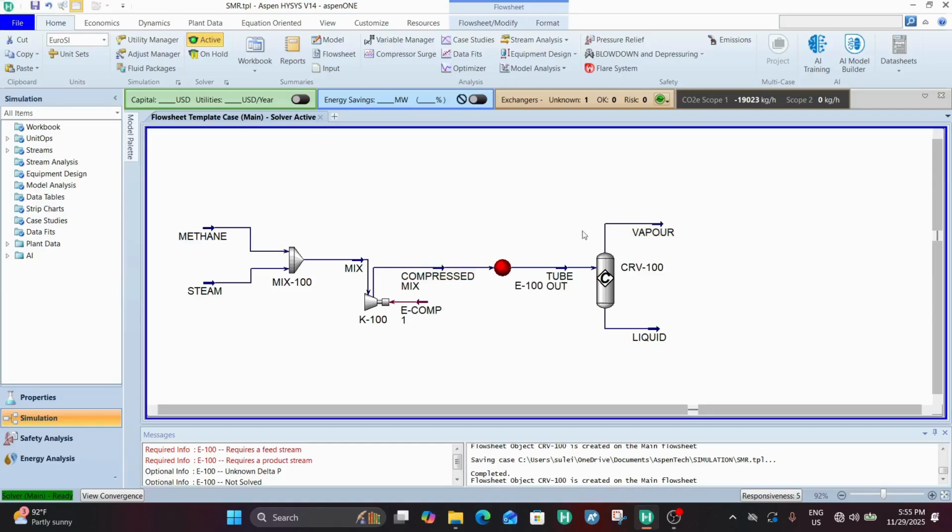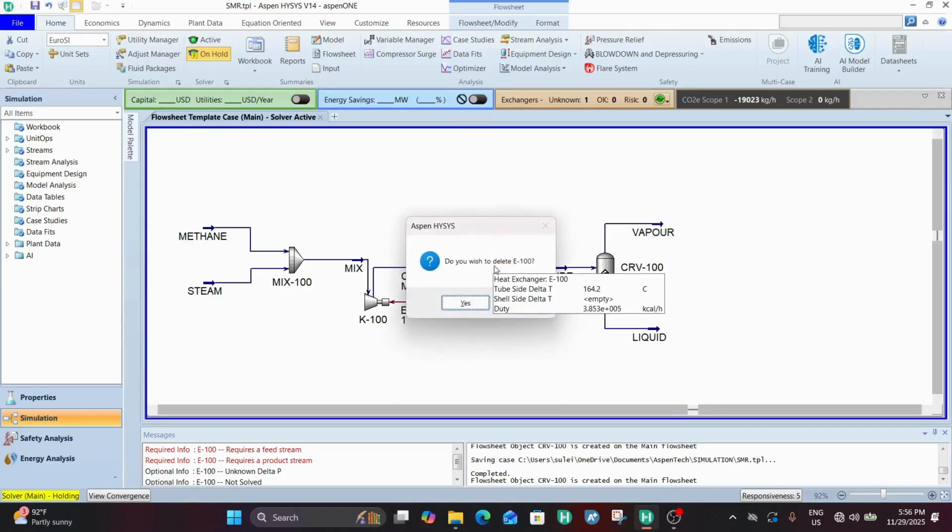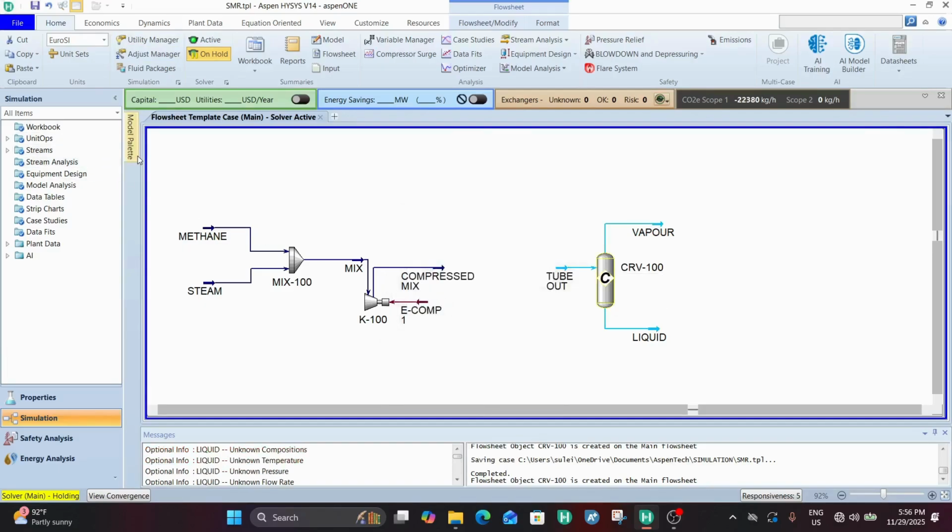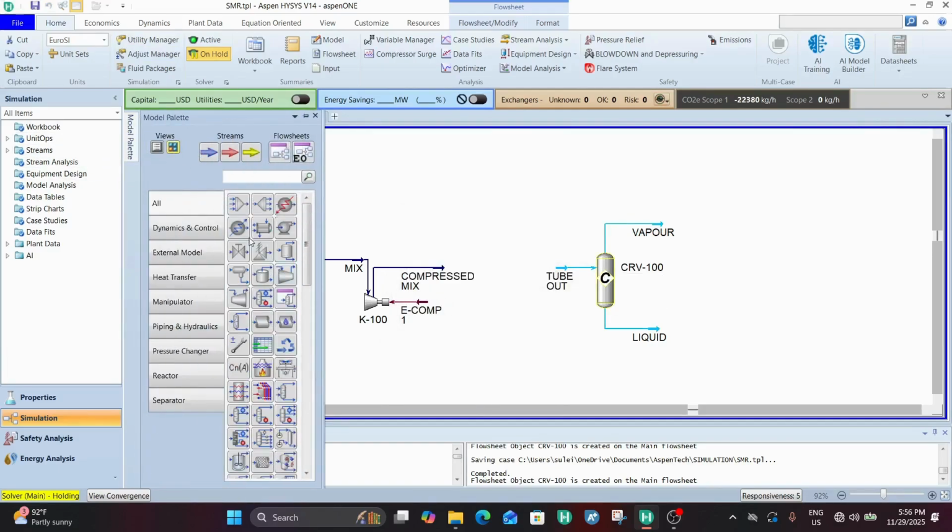So we do not have any heat to give the stream because the temperature here is lower. As such, if anything else, the opposite of what we need might happen. The heat from the stream would be sent down here. So that's not what we desire. Unfortunately, our optimization concepts would not work here. So we're just going to go on ahead and replace the heat exchanger with a heater.